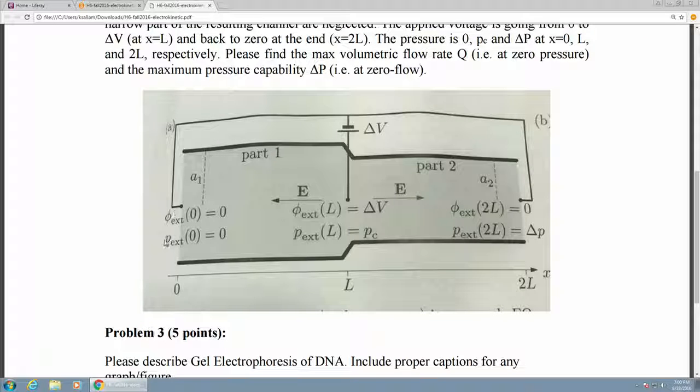And there is the pump. What's the job of the pump? Increase the pressure, right? Really, it provides flow rate at high pressure, not just increasing the pressure. You're not just building pressure at 0 flow rate. That's the extreme case. But the real function is that you deliver flow rate with a certain delta P, right? So you are driving the flow for the rest of the channel. Imagine you are doing, say, lab on a chip, and you're supposed to pump this liquid into multiple channels where they do mixing and they do reaction and stuff.